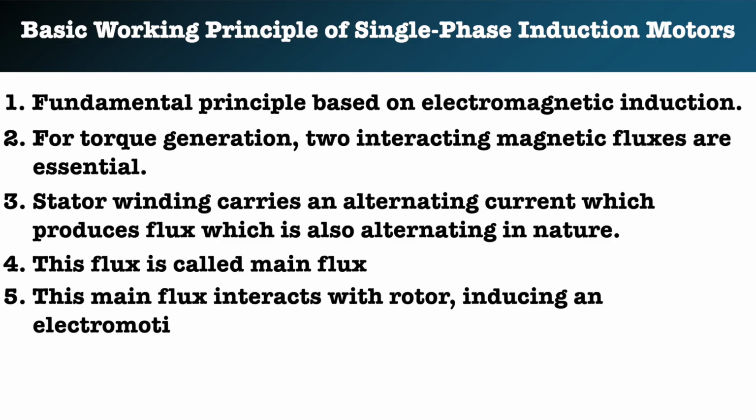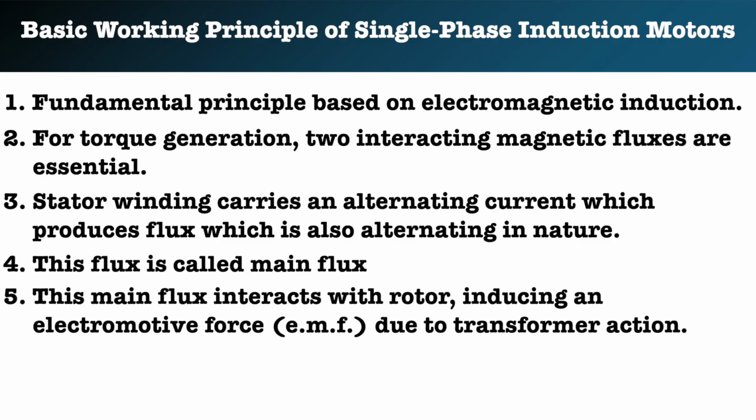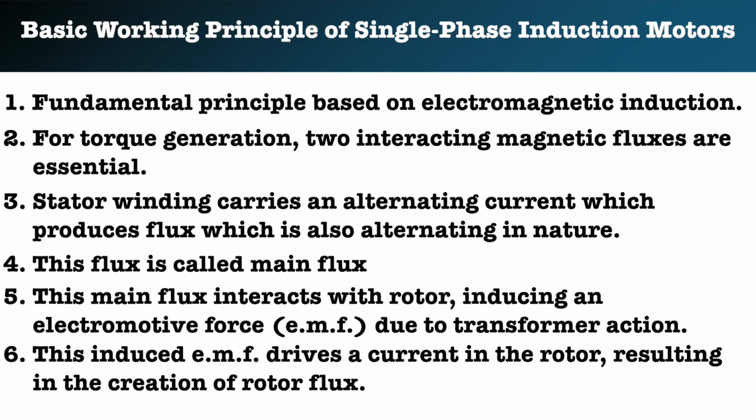This main flux interacts with the rotor, inducing an electromotive force or EMF due to transformer action. This induced EMF drives a current in the rotor, resulting in the creation of rotor flux. Thus, a second flux is produced according to the induction principle due to induced EMF, hence the motor is called an induction motor.